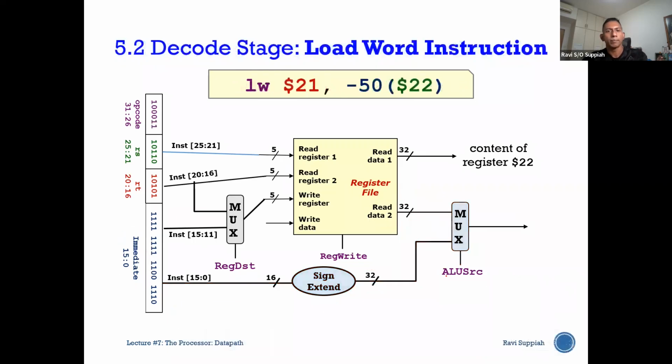All right. How about the load word instruction? Now, load word instruction, what are we doing? We are taking the RS, adding it with the immediate value, and putting it into the RT register. So this load word instruction is also supported with the current design that we have.